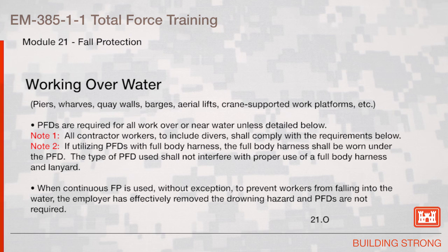Note 2. If utilizing personal flotation devices with a full body harness, the full body harness shall be worn under the PFD. The type of PFD used shall not interfere with the proper use of a full body harness and lanyard. When continuous fall protection is used, without exception, to prevent workers from falling into the water, the employer has effectively removed the drowning hazard and personal flotation devices are not required.